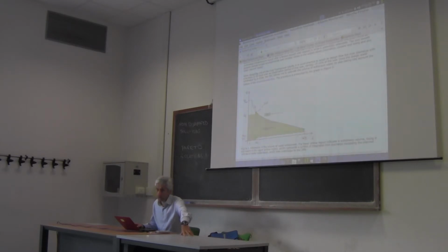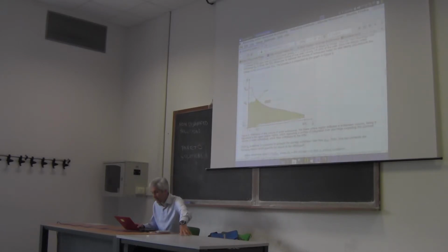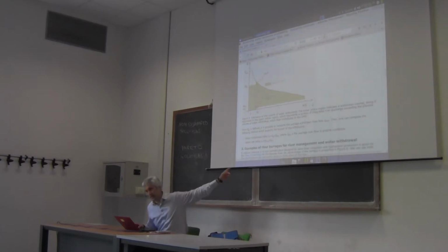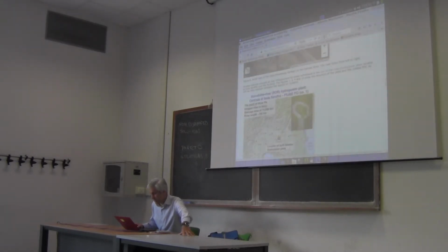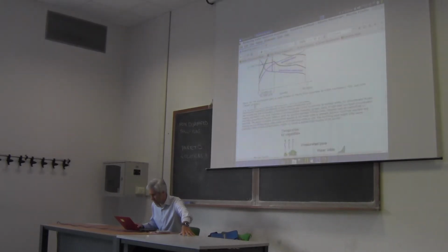Design water withdrawal. What is the typical design water withdrawal based on the flow duration curve? And we said a duration from 30 to 60 days. And another good question is this diagram: how to estimate the volume that is withdrawn from the flow duration curve. What is environmental flow? Another question. And this is not very analytic. I would say it's descriptive because I didn't give you any method for computing the environmental flow, but I explained what it is. River barrages, no, okay, here it's too early.